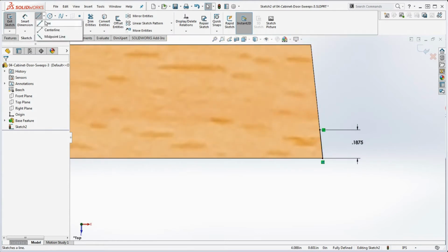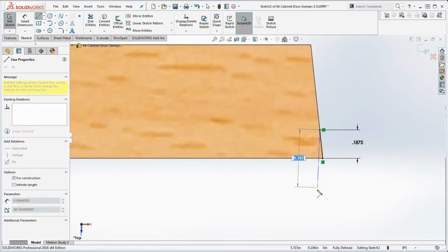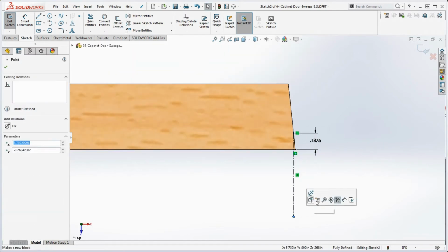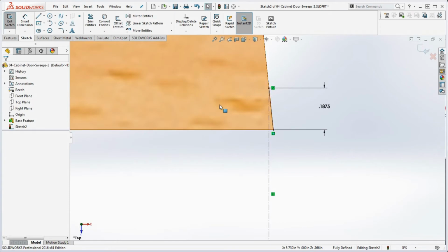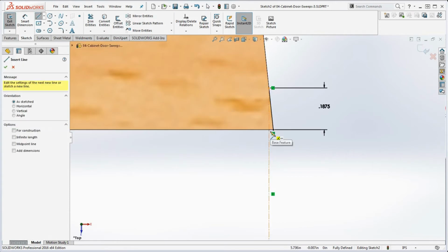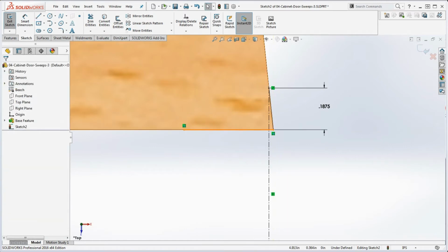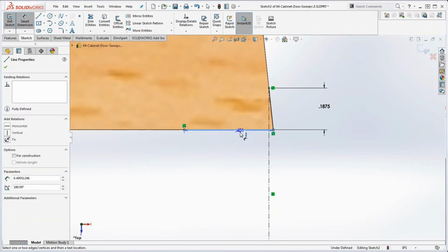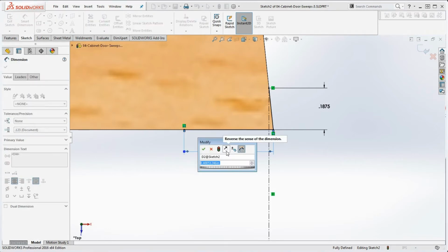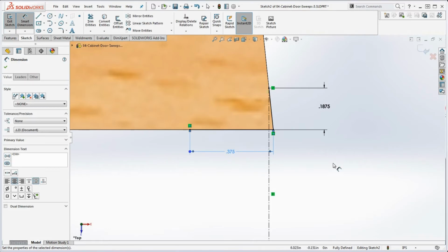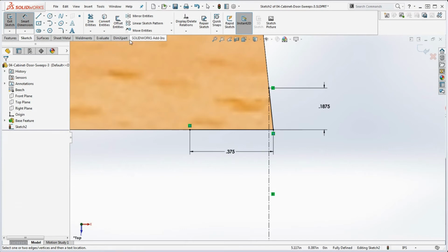So now we're going to take that center line. Again, the center line is going to be there, so we can actually dimension from that and provide other relationships in here. We're going to go ahead and sketch that arc on the top, but let's get this bottom line in here first. If we take this line over here, we can create that coincident relationship on that. And remember the distance on this line now, because that's going to be horizontal, we're going to create that dimension to be 0.375, I should say.